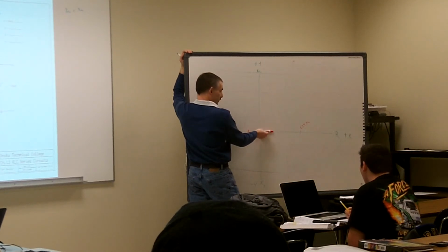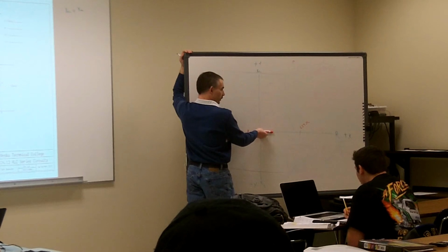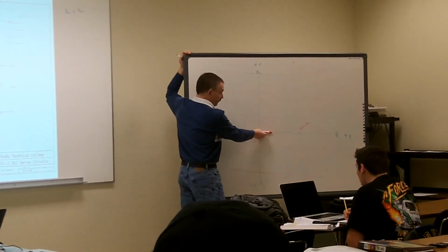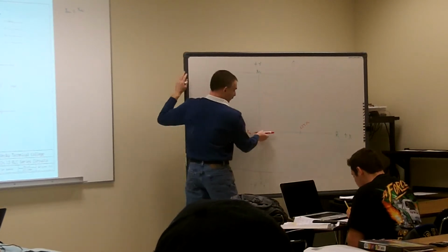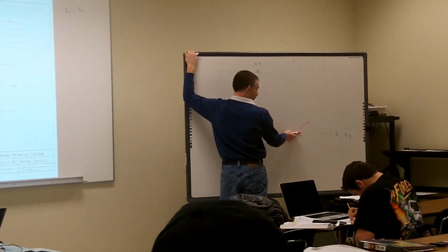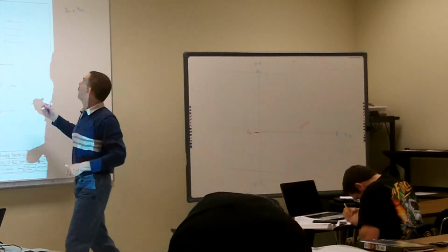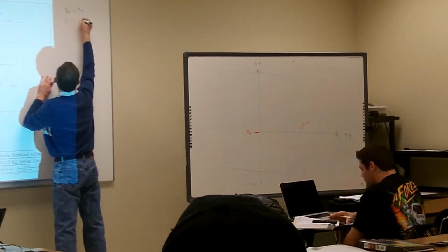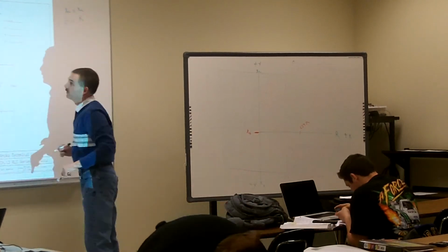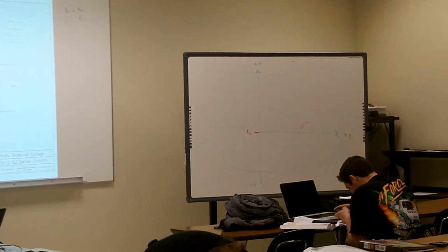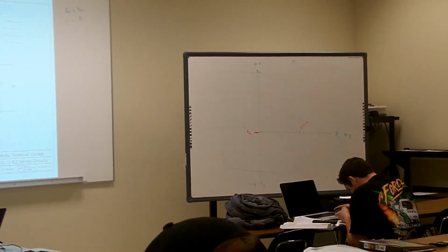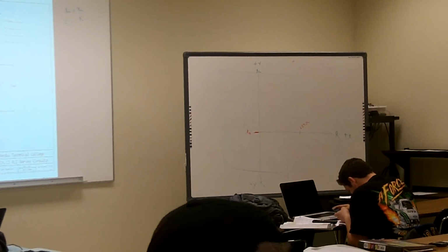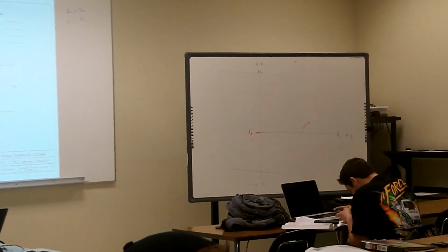If X of T is 0, and my resistance is 224 ohms, my Z is going to be right here, right? So my Z is going to be the same length as what? 224 ohms. Okay, so another thing: when we're at resonating frequency, Z is going to equal R. So Z, my total impedance of my circuit, is going to be 224 ohms. Okay?